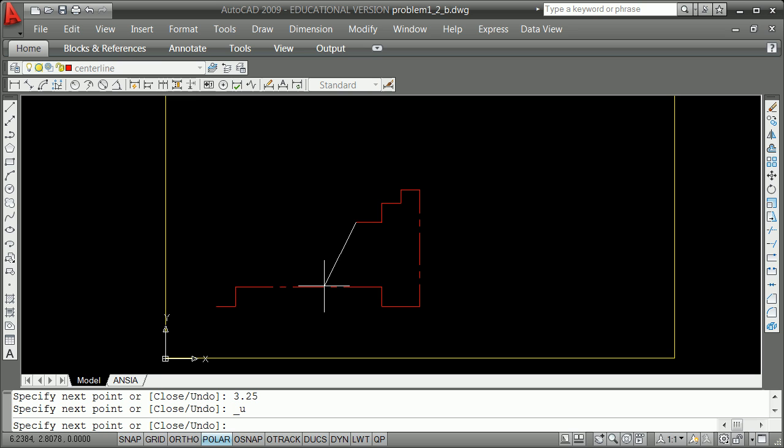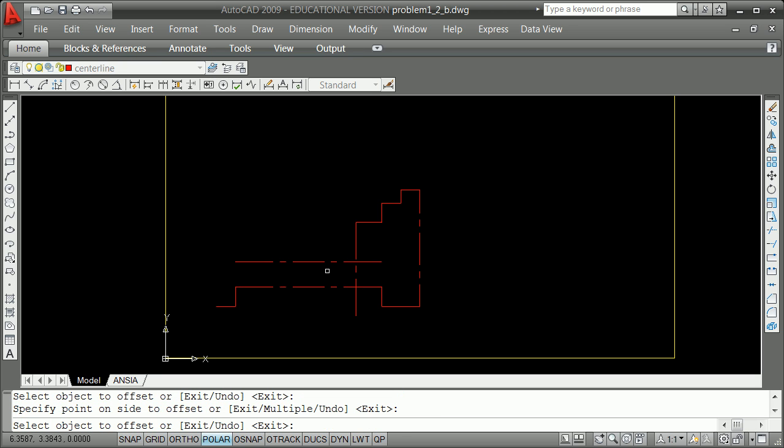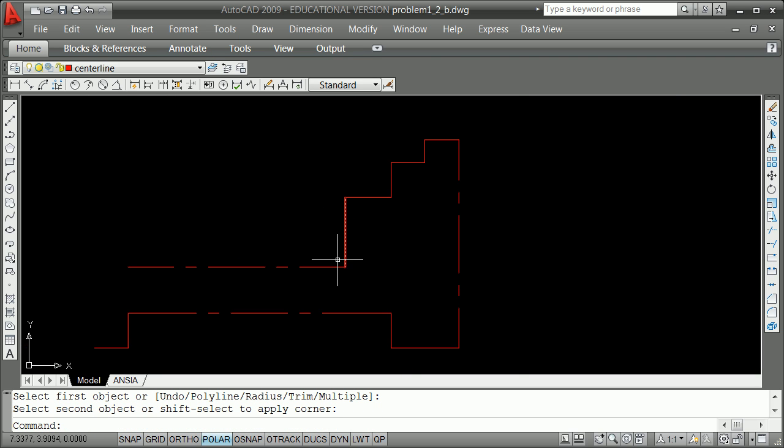So on the odd occasion, you could just do this now. Drag that line down, hit an escape, O for offset, 1, because it's a thickness of 1 along here, F for fillet, select, select, and you're back to that point that there's no one method.